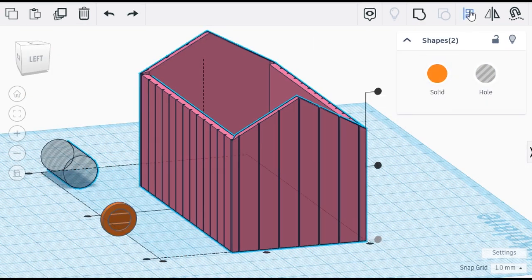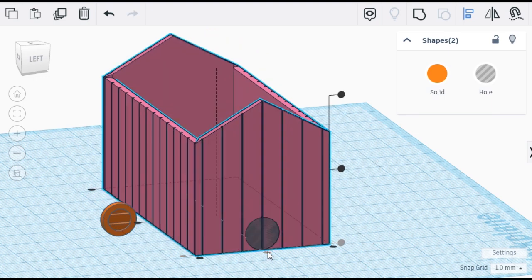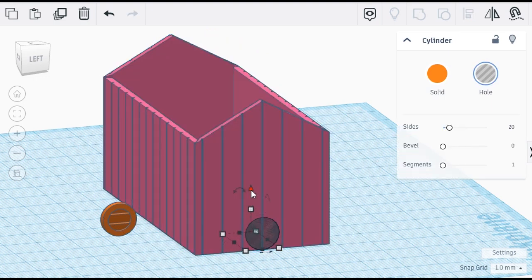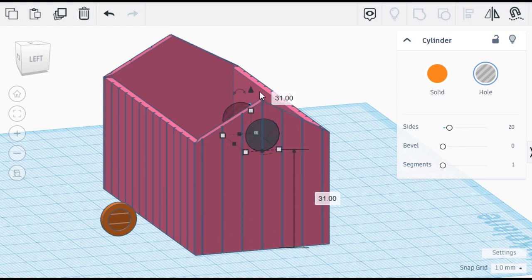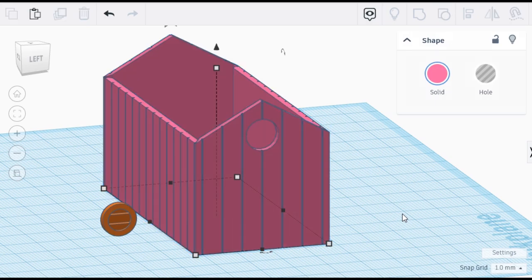Alternately, I use CAD to create a hole the same size as the louver but deeper, and then position the hole as a punch into the side of a wall prior to inserting a separately printed louver. This technique has the advantage of allowing you to create the louver in a different color than the wall without tedious painting.